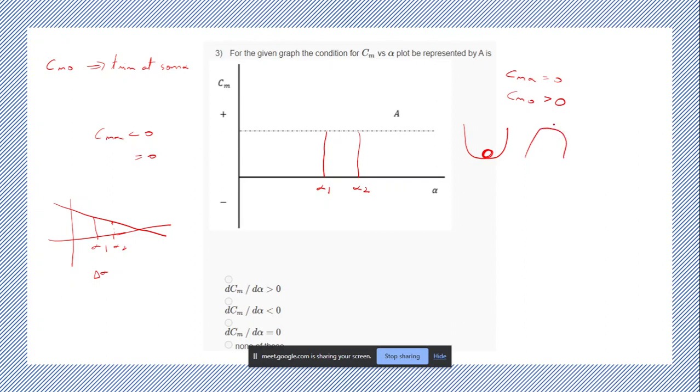If the ball is on an upturned vessel and you disturb it slightly, it will continue going away from the equilibrium. But if it's on a flat surface, you disturb it slightly, it will go to the new location and find its new equilibrium point over there and remain there. Okay, so this is statically stable, this is statically unstable, and this is neutrally stable. Statically neutrally stable. Okay.